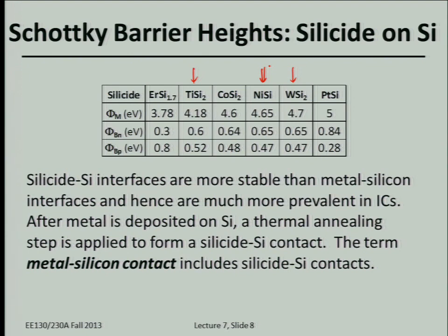If you deposit silicon as an electrical interconnect material, you deposit it over dielectric materials that are amorphous, so they don't have any crystalline structure. So when you deposit silicon on a random surface, it's not going to be a single crystal, right? It's going to be polycrystalline. So you can use very heavily doped polycrystalline thin films of silicon to form electrical interconnects locally, from one transistor to another. And that used to be done decades ago.